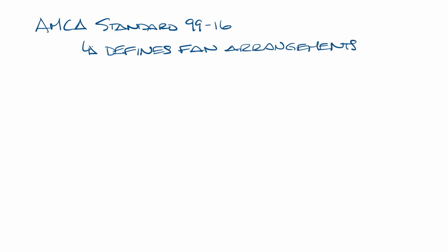AMCA Standard 99-16 defines the different fan arrangements. The arrangement is basically the orientation of the fan drive to the fan housing and wheel. It basically defines the way a motor drives the fan and how the motor mounts on the fan.